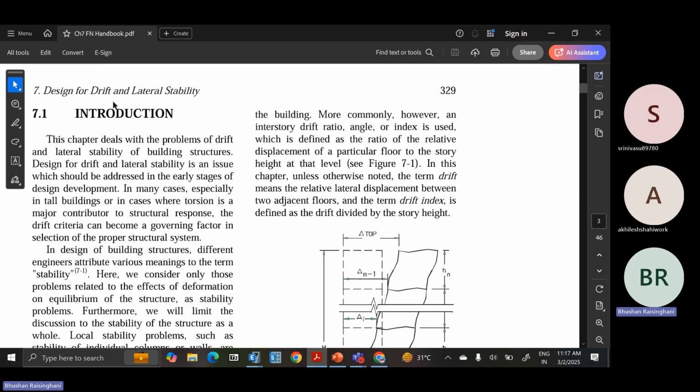By going through the cyclic nature, it has energy dissipation, and these deformations are captured in the form of the response reduction factor R, in which the important thing is ductility. So with higher deformations, the structure is able to take up to 1.5% drift before failure, as compared to the elastic drift of 0.4%, which is related to elastic instability. So there are two aspects of instability; I have explained how it is understood in lateral forces. Under the gravity load, what happens? There is a critical load, PCR. Now, what is this PCR related to?